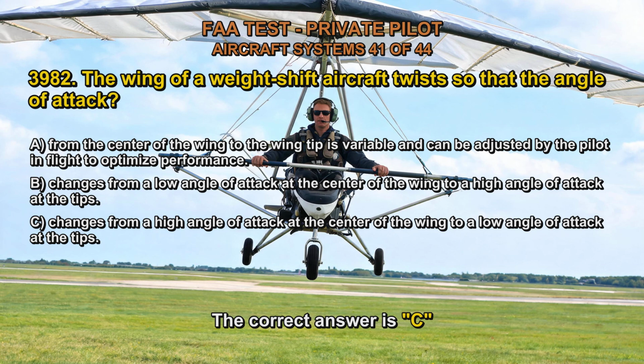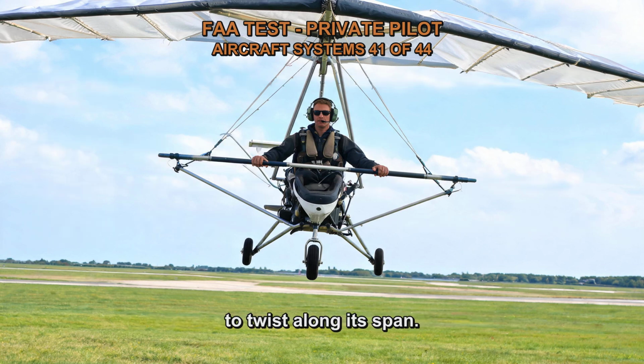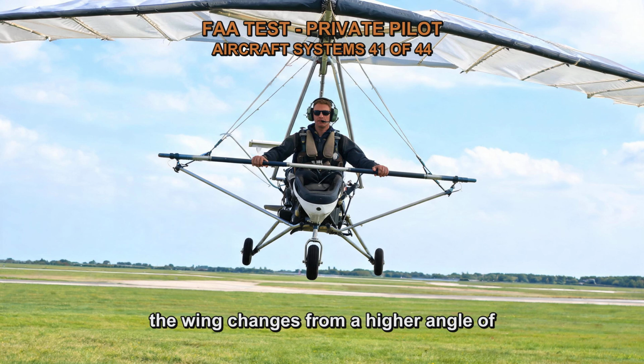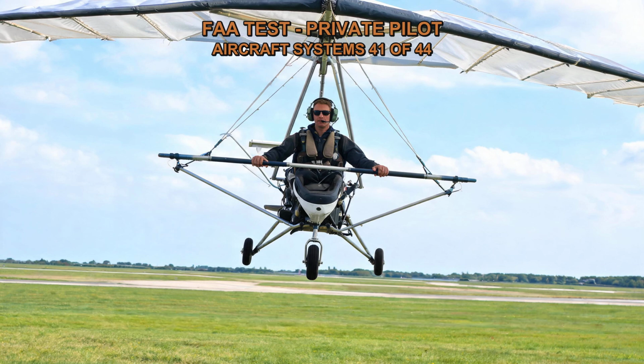The correct answer is C. In a weight-shift aircraft, the wing is designed to twist along its span. This means that the angle of attack of the wing changes from a higher angle of attack at the center of the wing to a lower angle of attack at the wing tips. This design is known as wash-in/washout twist.